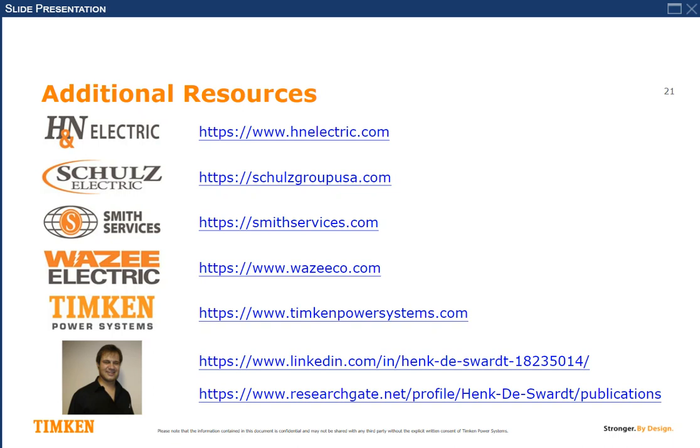You basically want to, when the insulation is degraded as far as it can go, remove the machine before you have a failure. Because if you have this 30 megawatt machine and you had a failure in the slot, it could burn a massive hole in the core, which might cause you to have to replace the entire core, which will cost you a fortune. So that is really just done on very large machines.